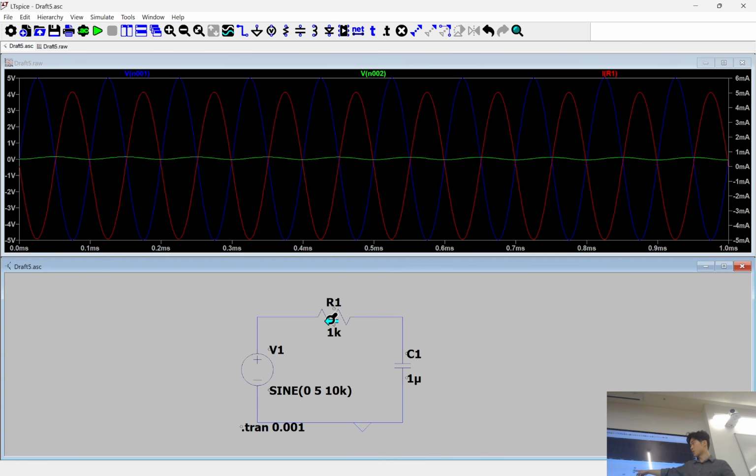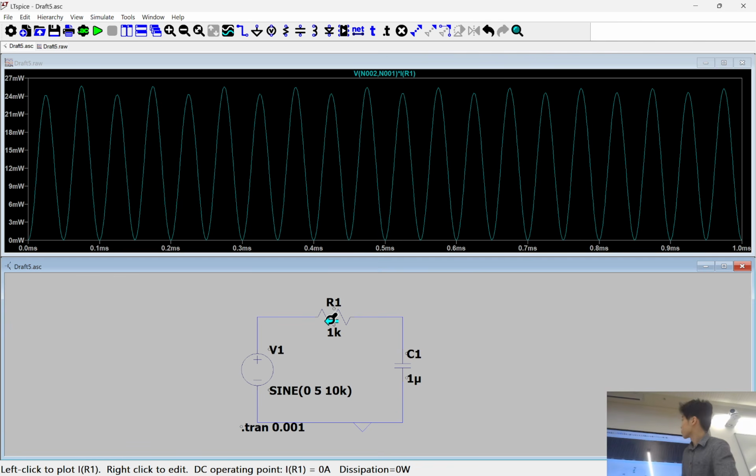You see it gives me this magnifying glass symbol with an arrow through it. In this case, you see on my graph, it's looking at the current through resistor 1. Something you can also do, on my computer, if you press Alt, you get this thermometer button. If you notice, it's the voltage times current. Pressing Alt is actually a shortcut to finding the power dissipated by a component as well. That's just another trick you can do.